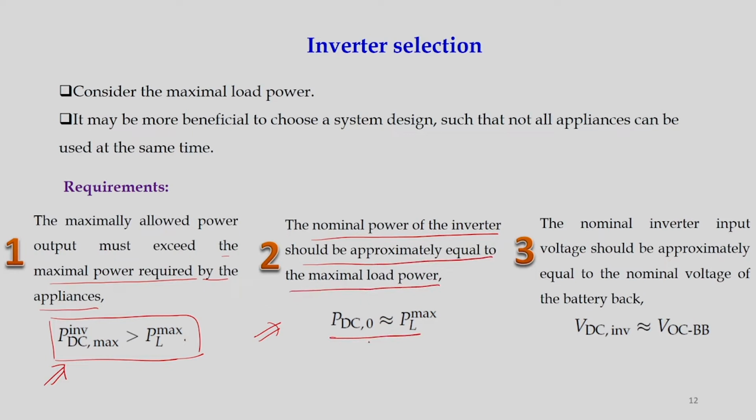The third requirement is that the nominal inverter input voltage should be approximately equal to the nominal voltage of the battery bank. This VDC of the inverter has to be equal to VOC of the battery bank, right.